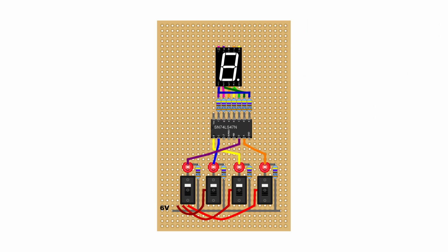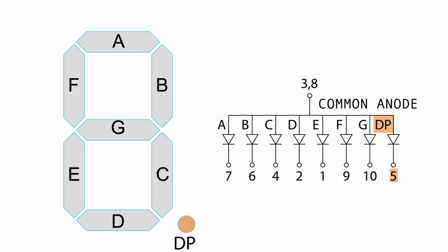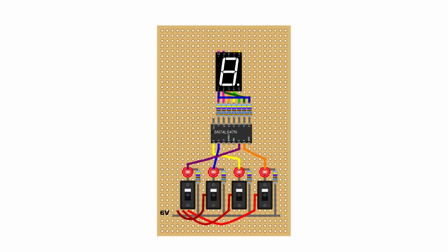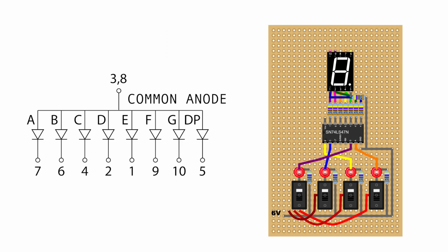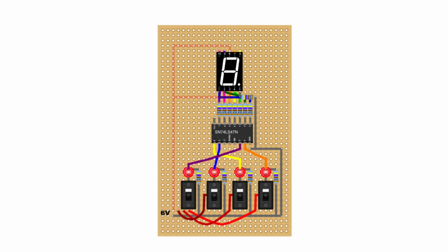Our display still has 3 pins open, 3, 5, and 8. This display has an extra LED for the decimal place, pin 5. You don't ever want to leave pins floating, meaning unconnected, so we'll connect it to ground so it's always on. And since it's also an LED, we'll use another current limiting resistor. We're using a common-anode display, and as usual, anodes are connected to power positive. So pins 3 and 8 need to be connected to the supply voltage. Okay, that's it for our display.